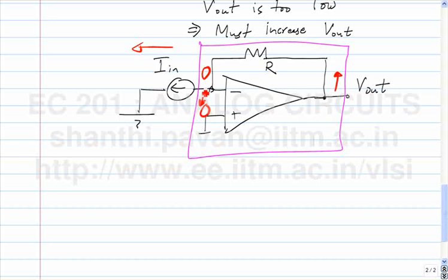This all happens very, very, very quickly. So in steady state, when you pull out In, this node potential remains 0. So for whatever value of In you pull out, you will find that the node potential at this node is always 0. Current source, it doesn't know anything except the fact that that node potential is always at 0. So as far as the current source is concerned, it is ground. Okay? And because you know what is inside the box, you know that this is not real ground, and this is called